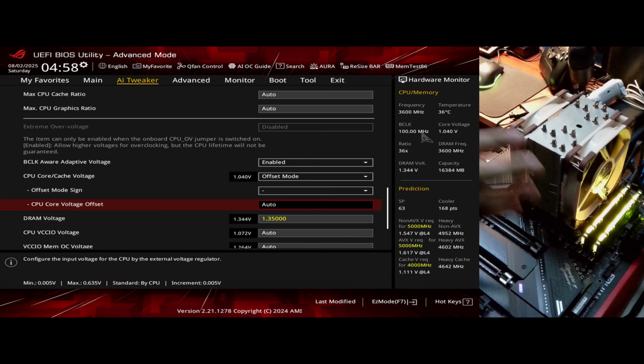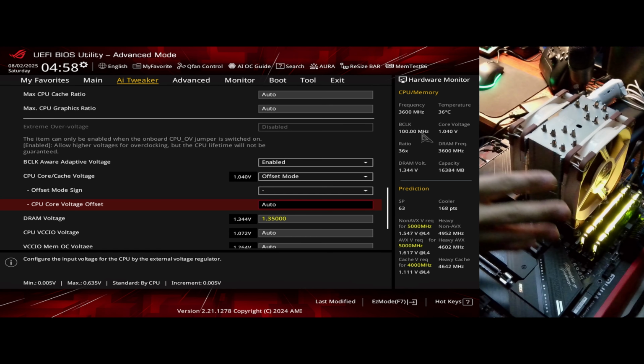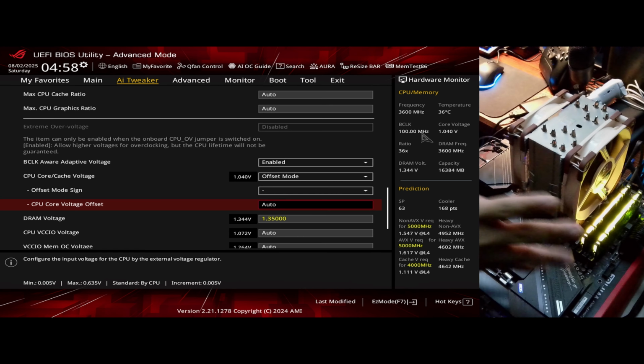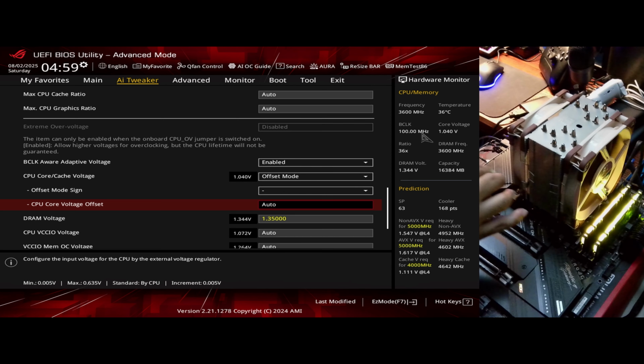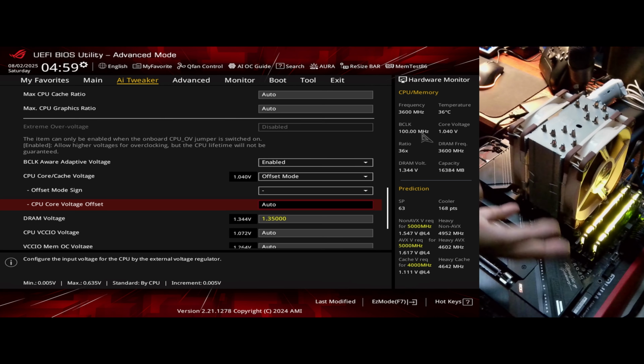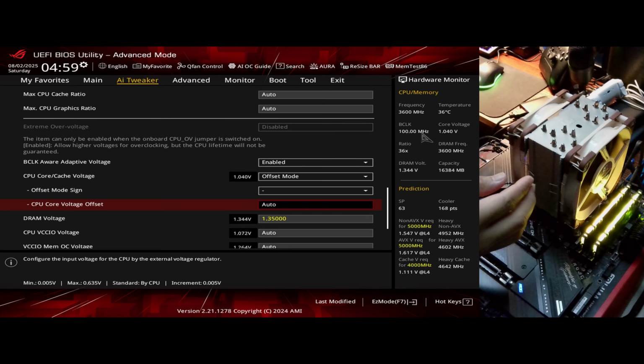So we'll see how much undervolting this CPU can actually take. We do all those voltage offsets. Each time it passes, we'll go back and offset a bit more, again and again, until we get maybe a blue screen, chances are. Then we go back to the last stable setting, so that we can have the stable undervolt, or the lowest voltage that this CPU can actually take, based on the silicon lottery of the CPU we got here.